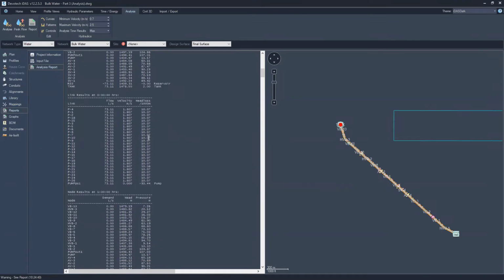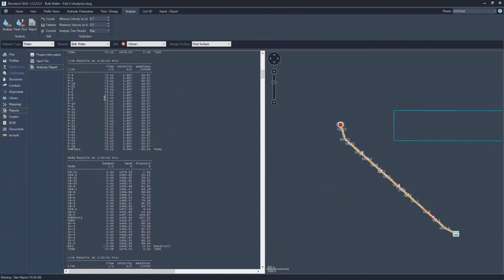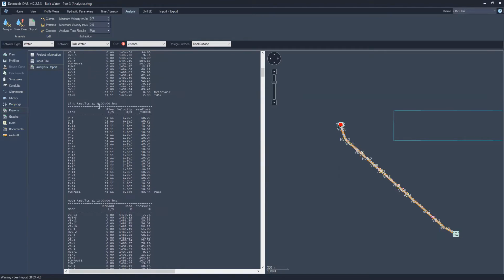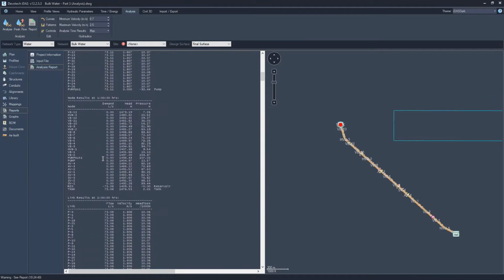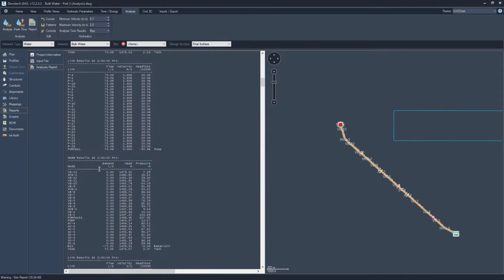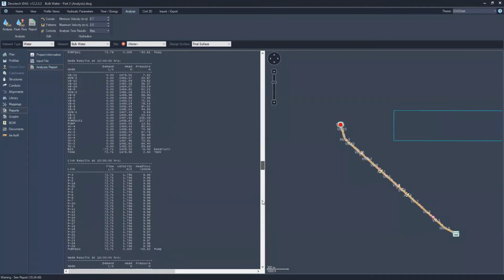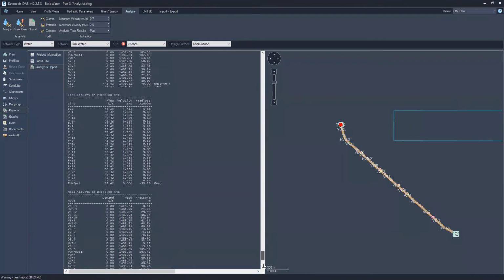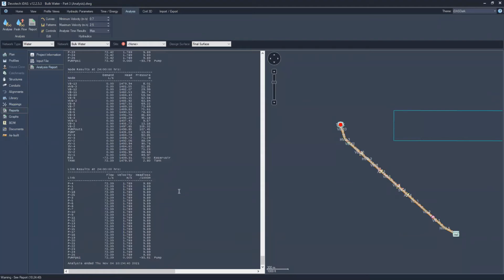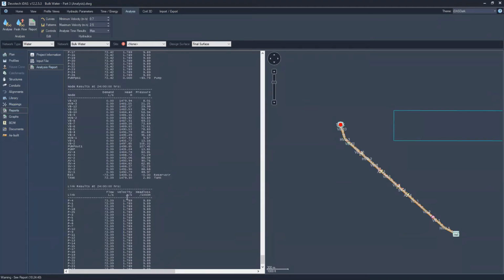All right. Head loss shows us our link results, and it shows us all of these results per hour. So it starts at 0 hours, and then 1 hour, node and link results, 2 hours, all the way up until the end. All right, you can see your flow in your pipes and so forth. Now do note this is very high.